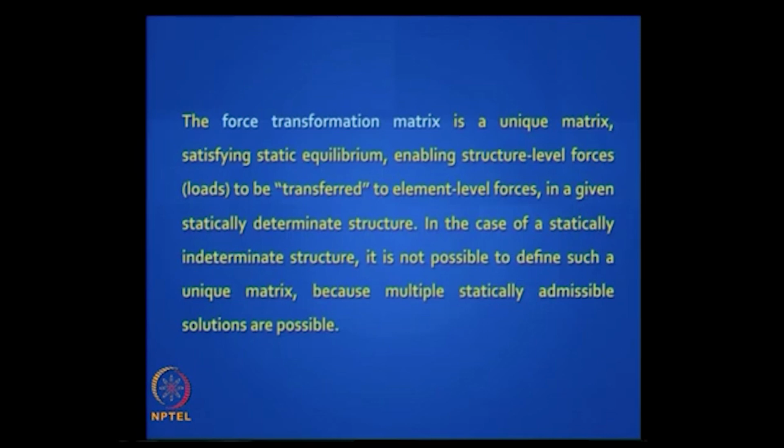The force transformation matrix is a unique matrix satisfying static equilibrium, enabling structure level forces or loads to be transferred, in inverted commas, to element level forces in a given statically determinate structure. In the case of a statically indeterminate structure, remember it is not possible to define such a unique matrix because multiple statically admissible solutions are possible. So how do you handle an indeterminate structure?